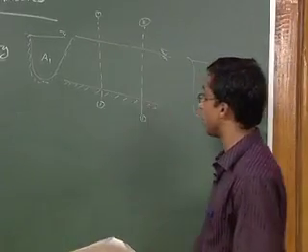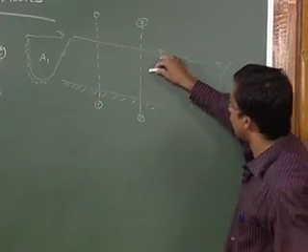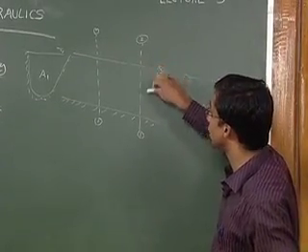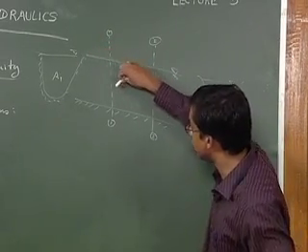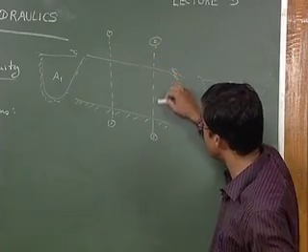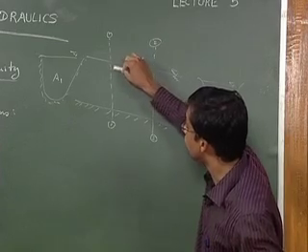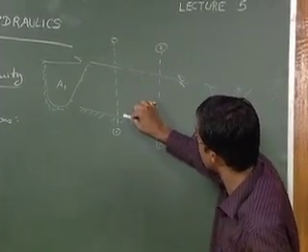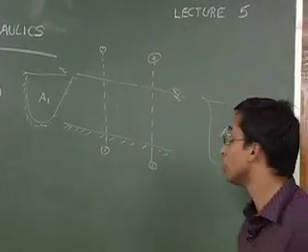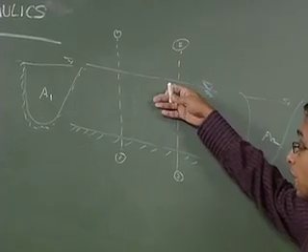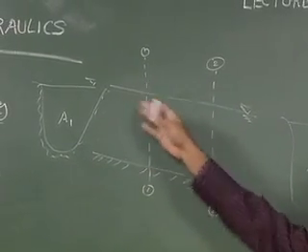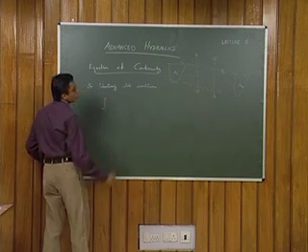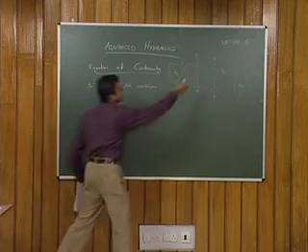So, the same thing we are again applying, or I can just again restate that the amount of water that is leaving out from section 2, this will be equal to the amount of water that is coming in from the section 1 and the rate of change of water stored between these two sections. So, between these two sections the amount of water stored is here. So, what is the rate of change of stored water in between those two sections? That will give you the difference between discharges in section 1 and section 2. We will again use the same equation, that is the amount of water or the mass of water that is coming out from section 2 in a channel.